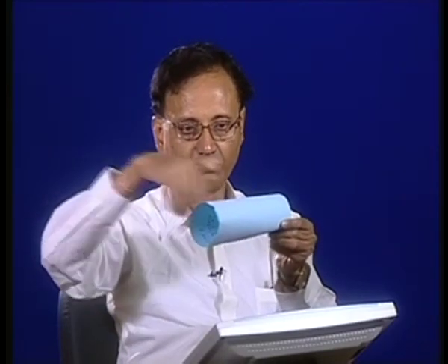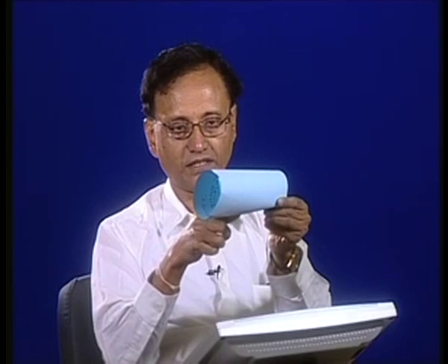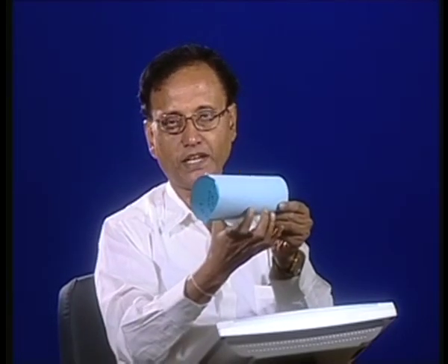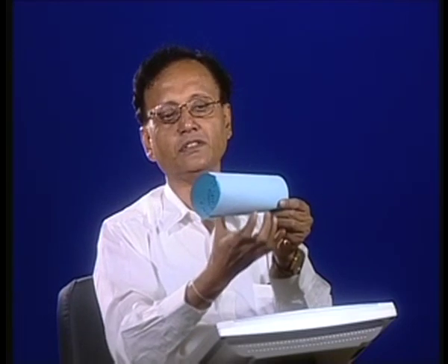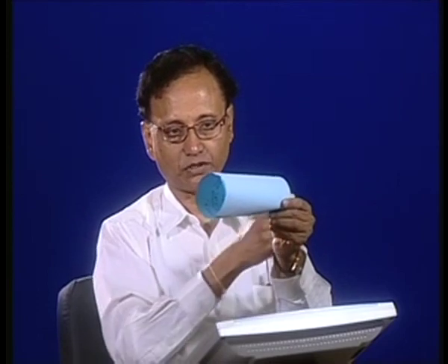There is a coil on top and a coil at the bottom. So, it will produce a magnetic field which acts perpendicular to the direction of the flow of the fluid, and we will put two sensors on both sides, one electrode here, another electrode there. You will see that due to Faraday's law of electromagnetic induction, some voltage will be developed across these electrodes. That voltage will be calibrated in terms of flow.